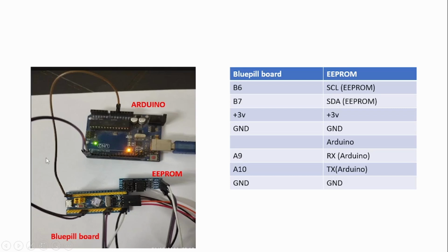Now again I would like to tell you not to use jumper wires unless it is just a temporary setup, because what I observed is that because of these jumper wires this setup sometimes gives garbage values, as these jumper wires are very loose. So if you have a proper application you want to develop, it is better to use a breadboard or at least some other good connectors.